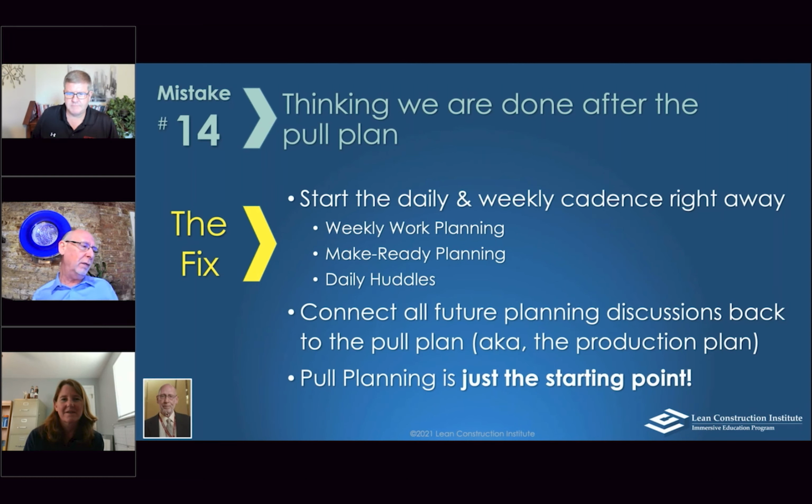This is a continuation of really the previous thought. Being done with the pull plan, what do we have to do? We have to take it and translate it to all the other plans that are functioning at the time. There's a weekly work plan, there's a make ready work plan, and there's the daily huddle. So we have the six-week lookaheads, we have the weeklies, and we have what we're doing as a result of the weeklies, the quick tag and touch of are we on, are we not on? All of that sequencing has to, again, if you remember what I said about what that pull plan wall is, it is an illustration of the commitments being made. That's all it is.